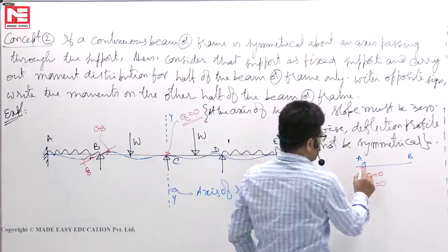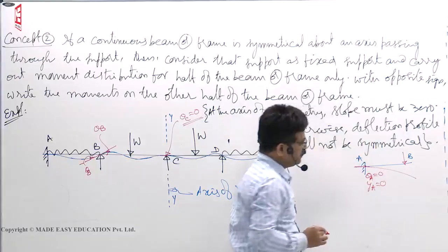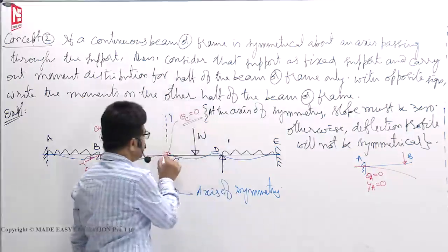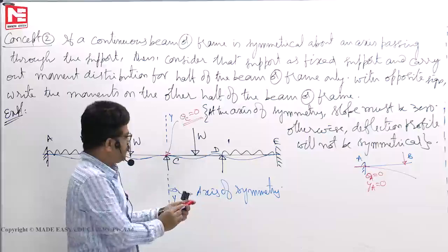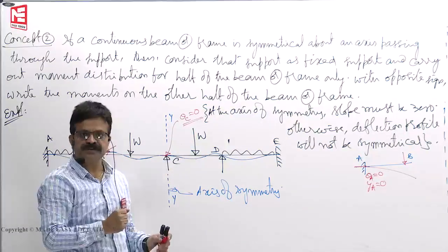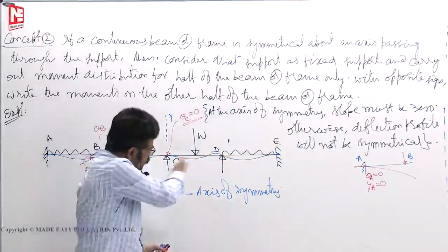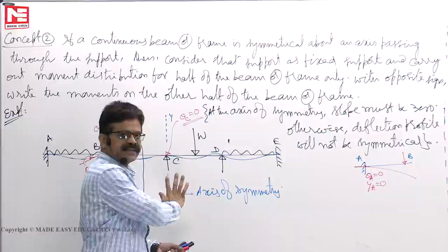Here also, if at all due to some point load, it will deflect like this, say. Here deflection is 0, slope is 0. Here also deflection is 0, slope is 0. That means I can cut, throw it out, and take it as a fixed support. Once deflection profiles match, then corresponding to that we can take it and stick it here.